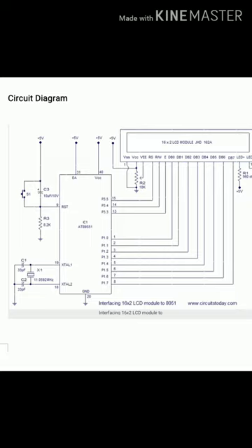So what it means? It means that whenever the microcontroller wants to send either the command or the data to be displayed, it has to send that particular data through port 1. And where will it get received? It gets received at DB0 to DB7. Fine. So that is the 8-bit data line interface that has taken place.